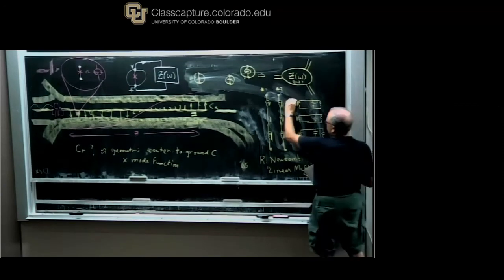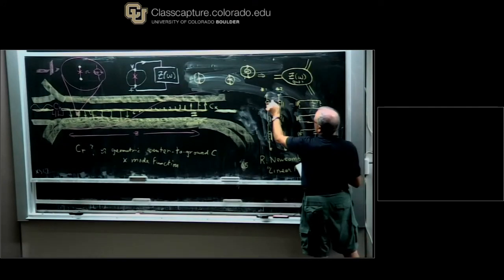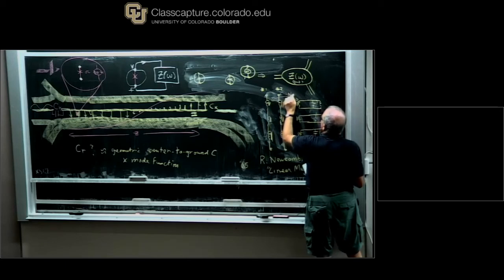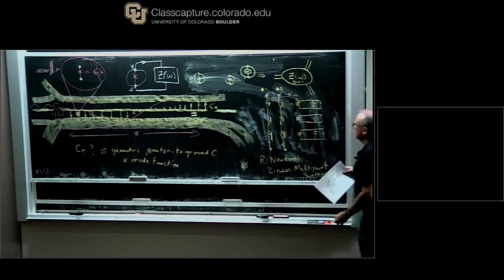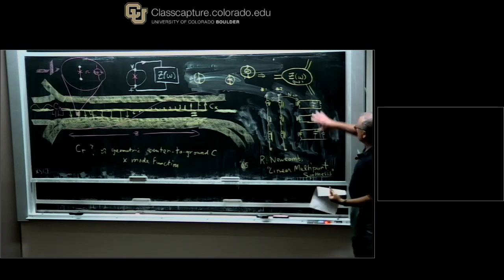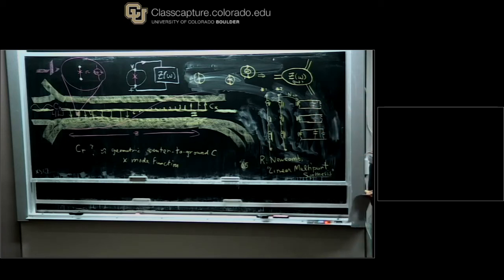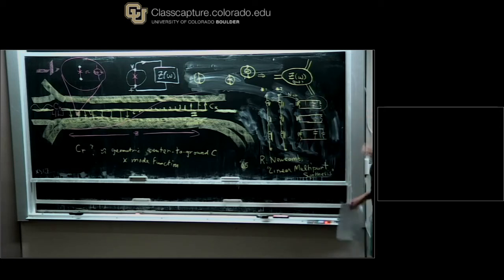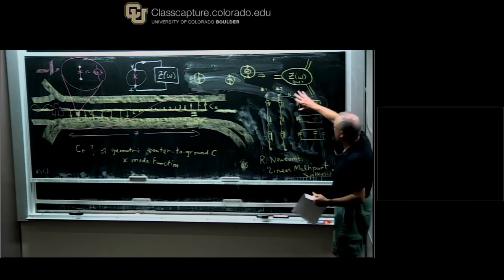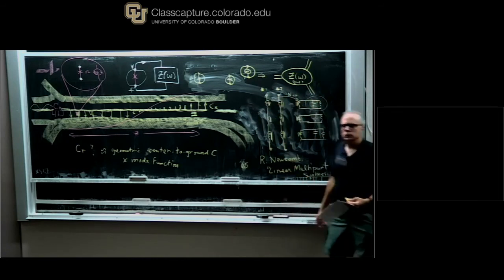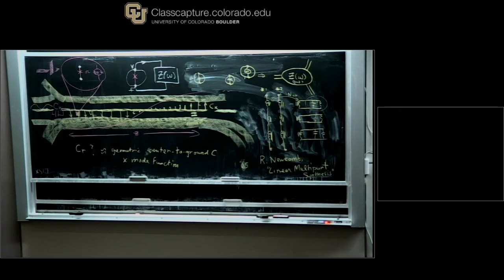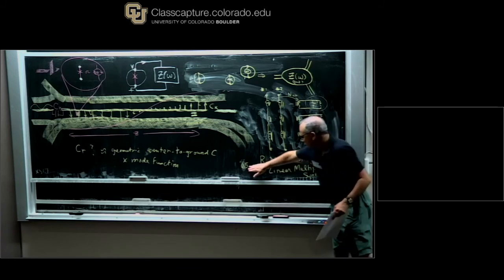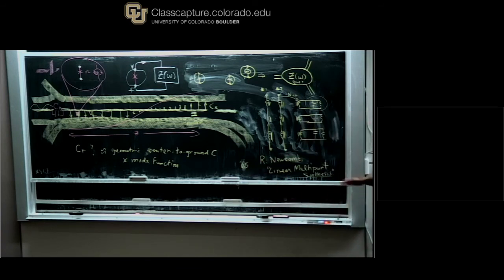And these transformers, they all have turns ratios, N, A, B or something. So the whole network of turns ratios. And they determine what you might call the participation ratio of this. Say this is the one resonator. This is somewhat getting to your question. Here's one resonator, and it's seen by each port. But the participation ratio of each port is different. That's the new physics language for this. The 50-year-old or 60-year-old electrical engineering language was simply that there are turns ratios of an effective transformer.